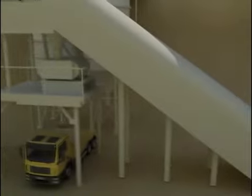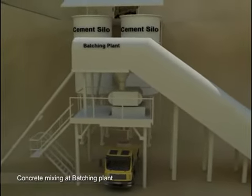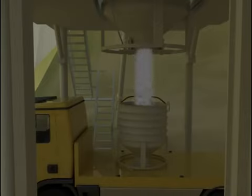for mixing. At the batching plant, aggregates are mixed with cement coming from the cement silos and chilled water in the required proportions to make a concrete mix of the desired consistency. The concrete thus made is transferred into the concrete bucket placed on a truck that carries it to the dam location.